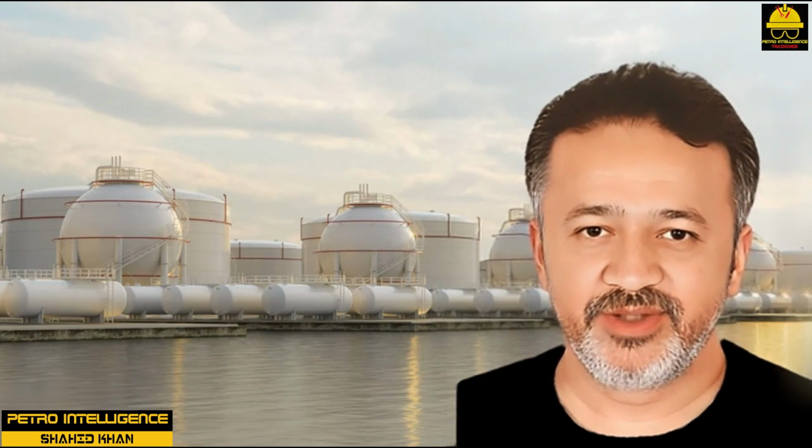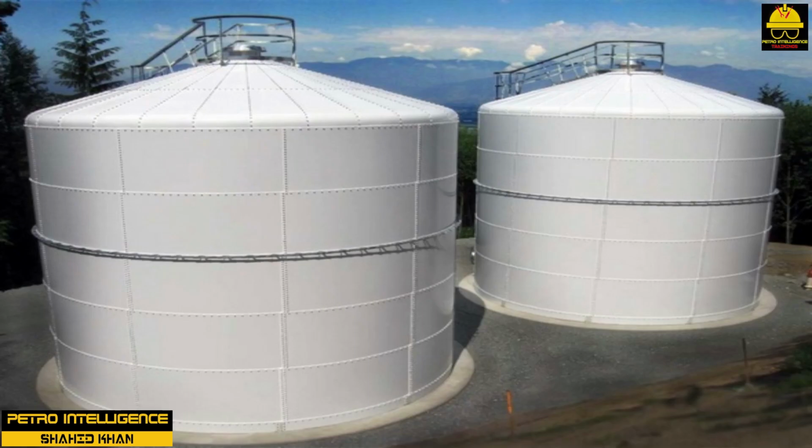Cone roof tanks, low to medium pressure. A cone roof tank has a fixed, slightly conical roof, one or more inside support columns, and a flat bottom. Cone roof tanks are used to store low vapor pressure stocks. Cone roof tanks are designed to operate within a range of about 1 inch of water pressure to 1 inch